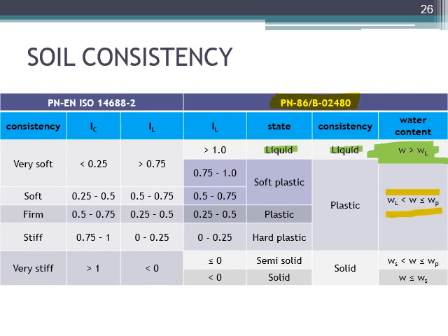Which one it is, it depends on the value of the IL, so the liquidity index. And actually, you can say that the range between the plastic limit and the liquid limit, which are exactly here. So here at this value, we have the plastic limit, while here we have the liquid limit, right? So if the water content is somewhere in between these two values, the soil is in plastic consistency.